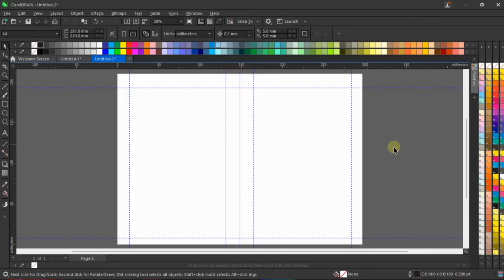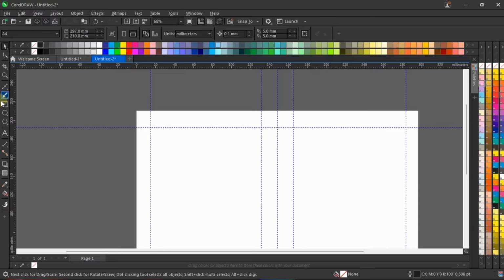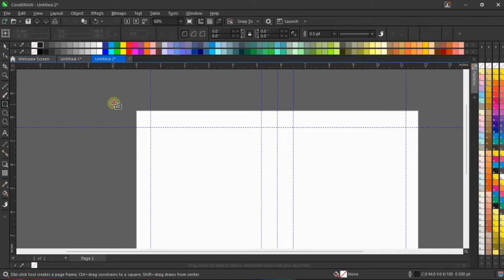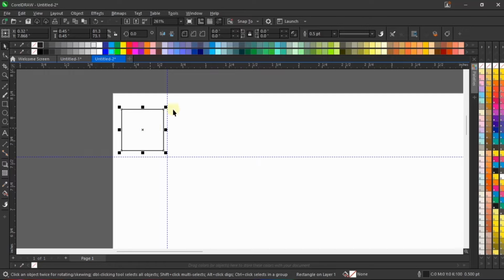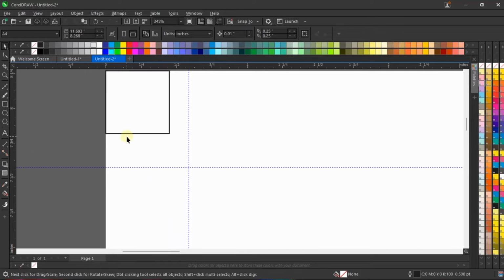I will answer you. Now I am going to measure this same page the same way I did that of the inner jotter. How will I do that? Remember, we use 0.4 inches. So let me select inches, change my unit to inches, draw the small box. On my property bar, look at where I type 0.45 by 0.45. I'll press enter. So I've been able to get this small box here. Have you seen? So click on the box, click on the shape, press letter T and letter L. T for top and L for left.